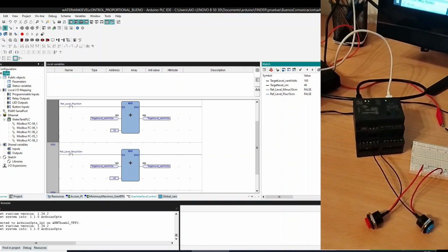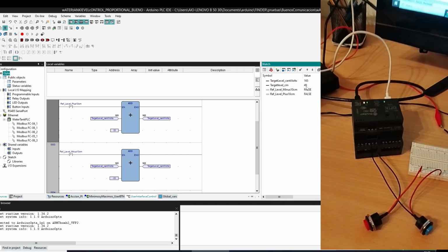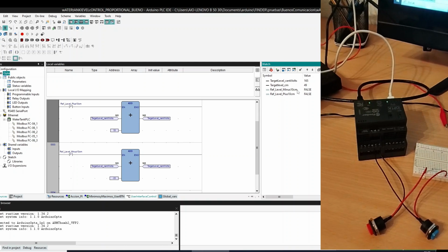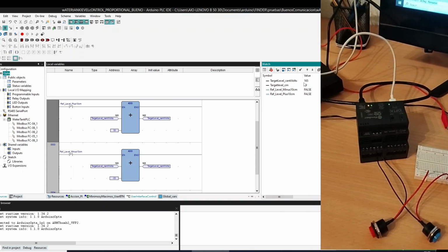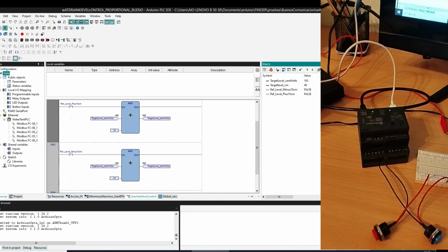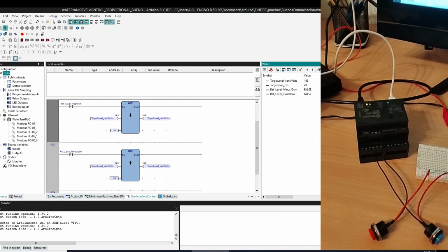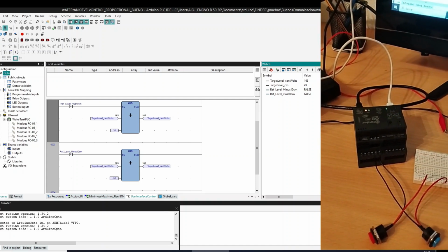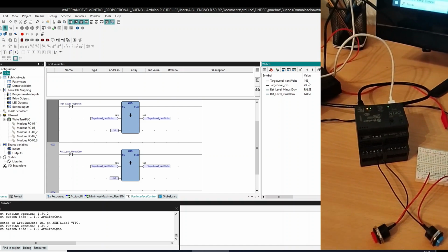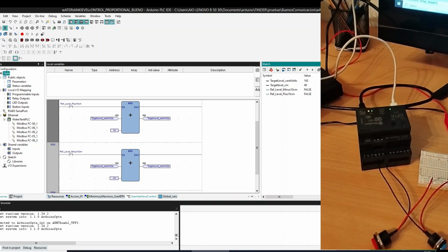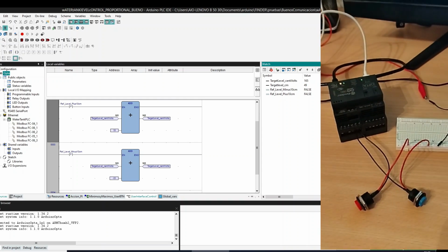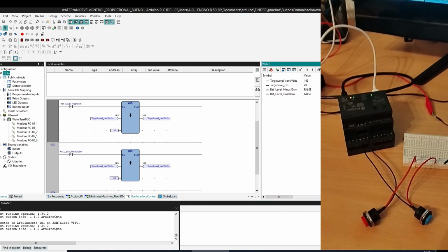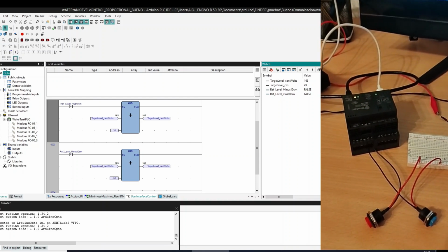And like that, that's how the user will be able to choose the target value that he wishes the water level to have. In this case, we wish to have 49 centimeters, which equals a wished read signal on the water level meter of 165 centivolts. That's what we wish to read. What we actually read has nothing to do with what we wish, and that's the source of the error that we will try to correct with the PID control.